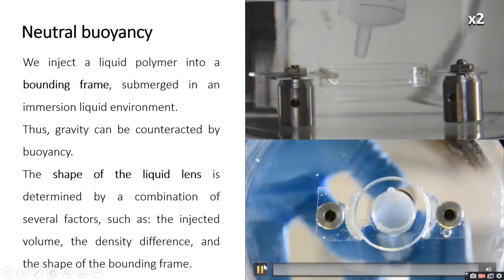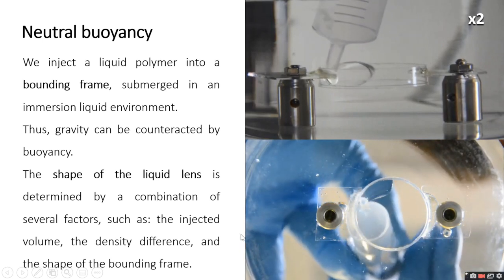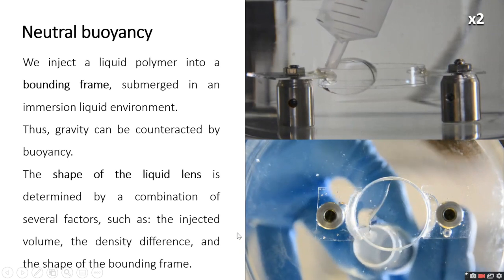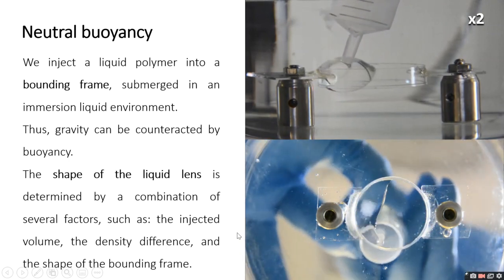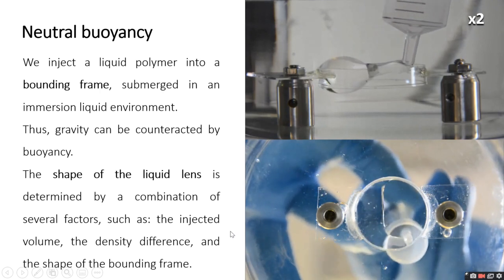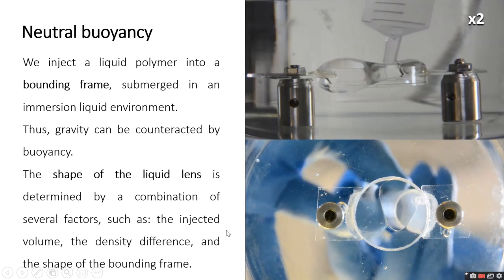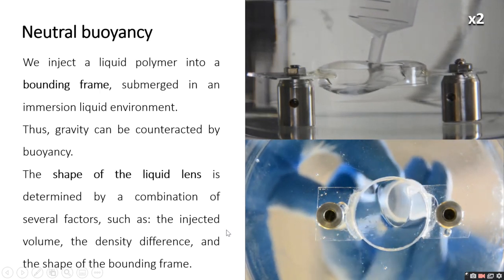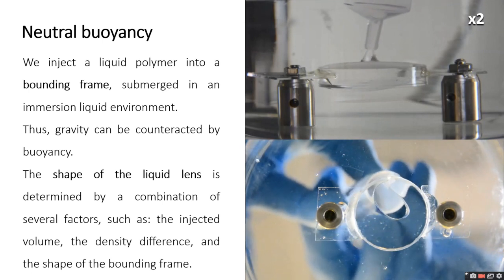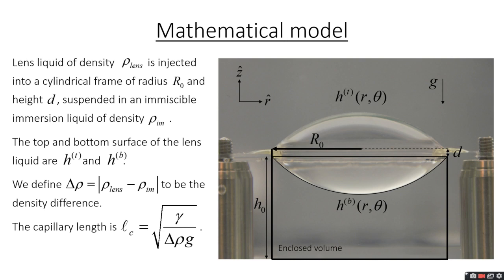This brings us to the second obstacle of making fluidic lenses, that is the shape of the lens. Obviously, we don't want to make actual droplets, but rather lenses, and preferably with more interesting shapes than just symmetrically spherical. There are two main parameters that allow us to control and vary the shape of the lens. The first one is again the density difference, which we can vary near its neutral buoyancy value. And the second one is the geometry of the bounding frame. So let's see what it looks like theoretically.